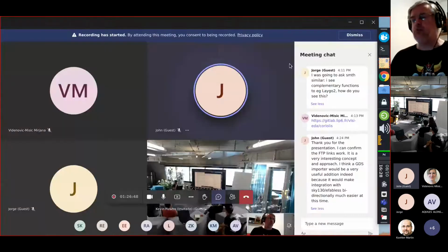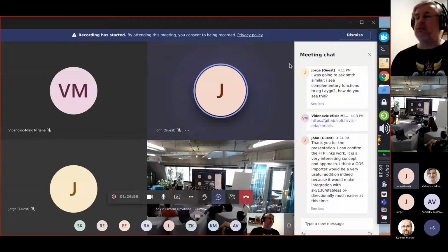So this is how we perform the technological portability. This is not perfect because sometimes there are new rules that pop up. The stack generator can only take into account rules that I know and understand. But sometimes with newer technology or corner case technology, you may have some rules that pop up, and then you may have to edit the stack script to take into account those new rules. But it shouldn't happen too often.